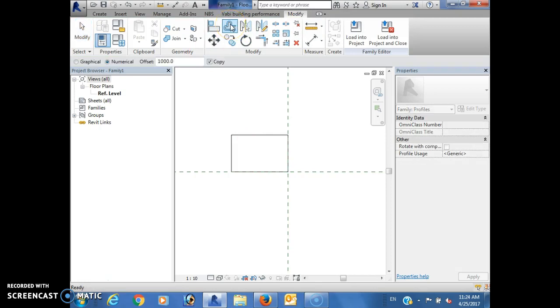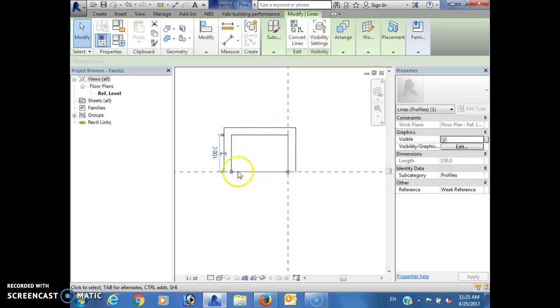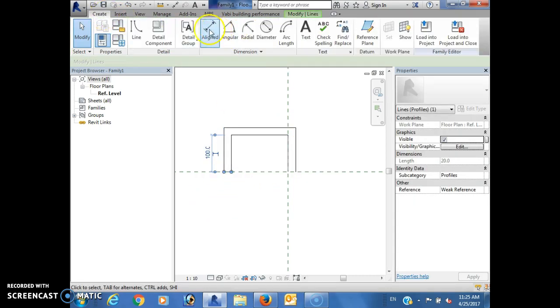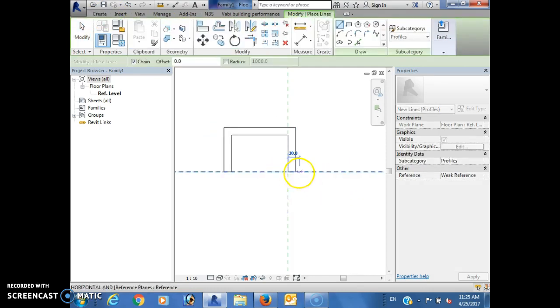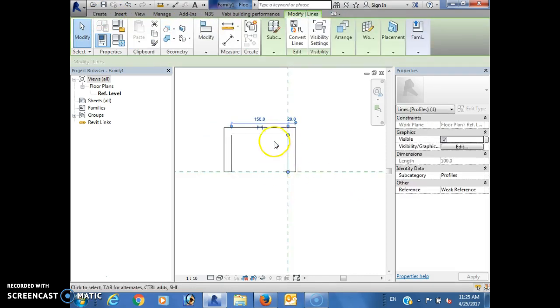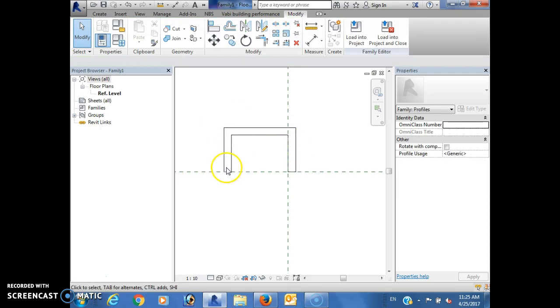And now the thickness of the coping, I want it 2 centi. It's going to be ceramic. So I go like this, a 10, 15, and then I'm doing offset 2 centi outside. 10 and 15 is the inside, and 2 centi all outside. The line has to be closed. It has to be a closed loop. If I press Tab, you see that everything is highlighted.